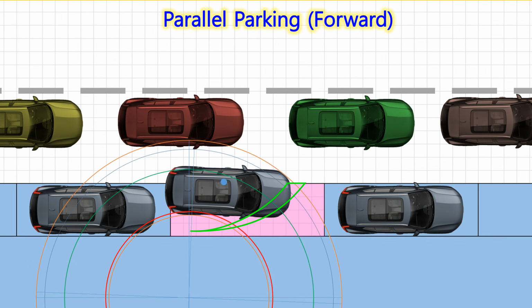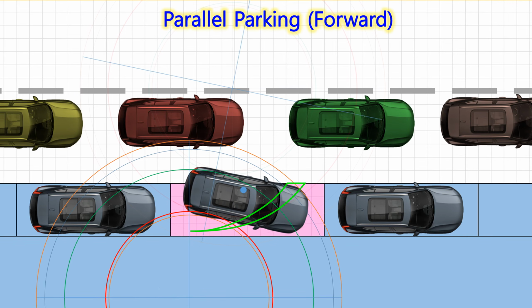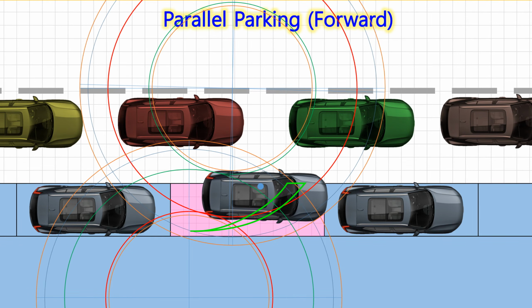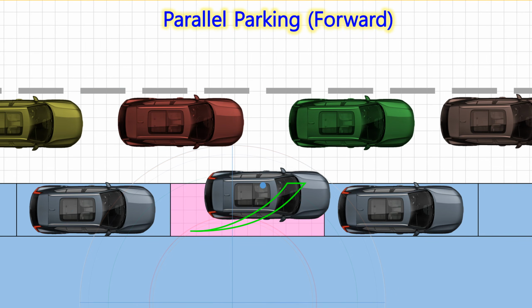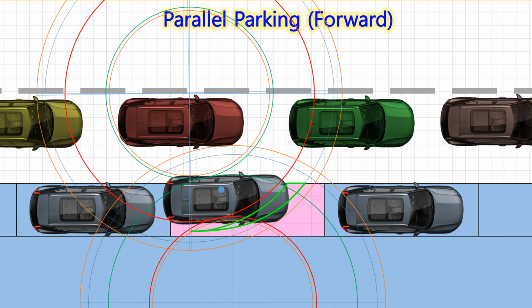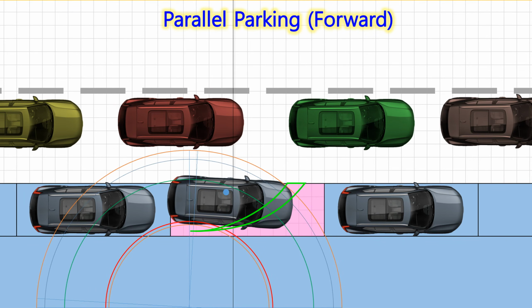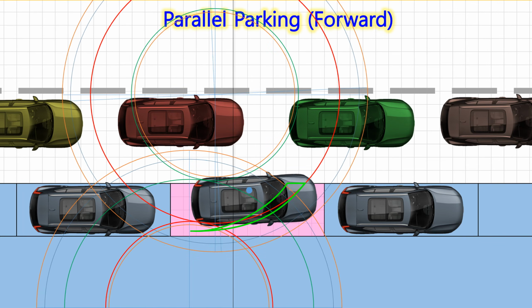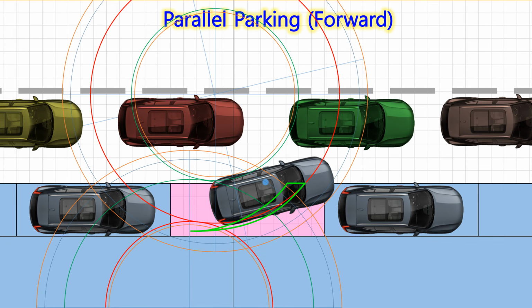It proceeds repeatedly in an S shape, and at both ends, the car must be perpendicular to the direction of movement. It moves little by little laterally. If you don't make an S shape, you'll keep going back and forth in the same place. At last, the right rear wheel entered the green zone. We will be able to complete parking soon.